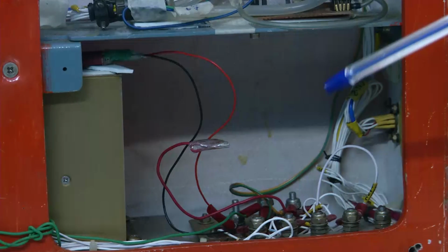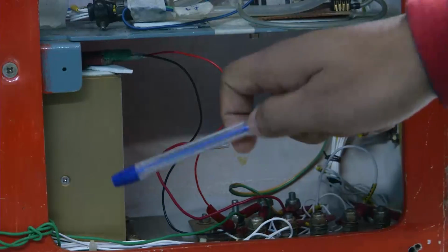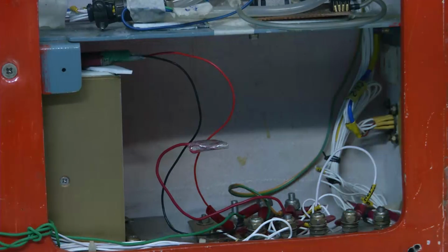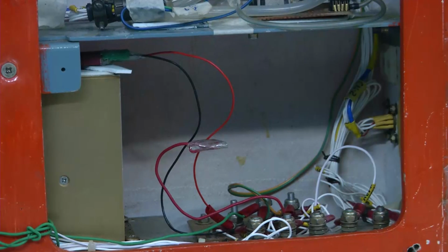Now as far as accuracy is concerned, your IMU can measure acceleration up to plus or minus 4G, with an accuracy of less than 0.5 G. Regarding your roll and pitch angles, roll can go from minus 180 to 180 degrees, whereas pitch can go from minus 90 to 90 with an accuracy of less than 0.1 degrees.